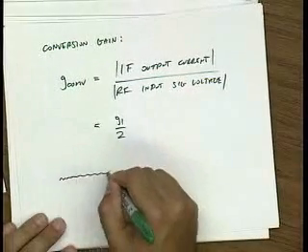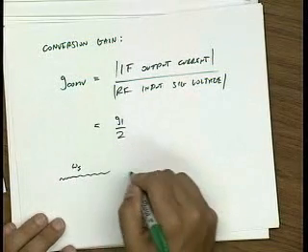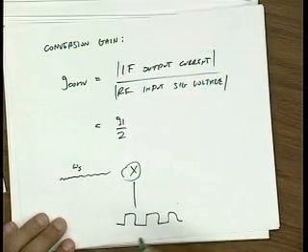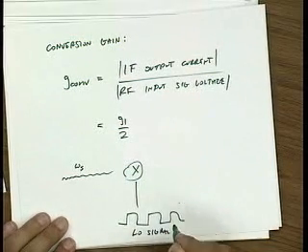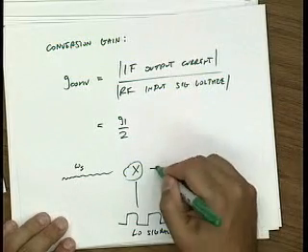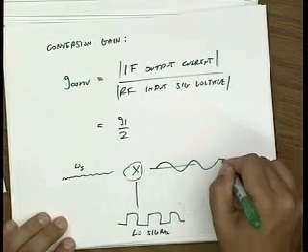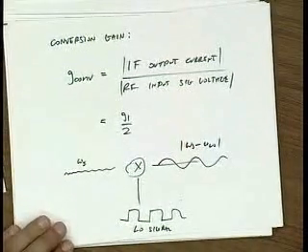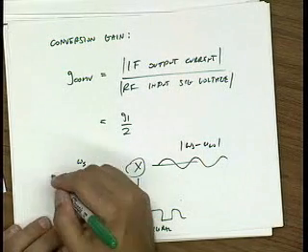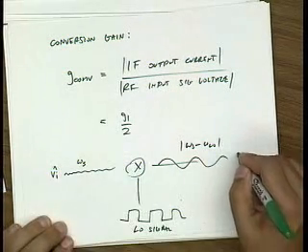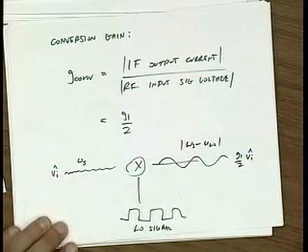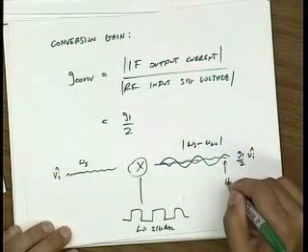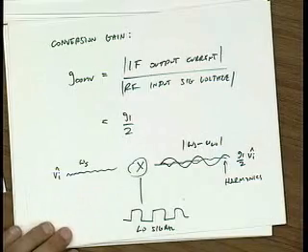So the input is small, at frequency omega s. It goes into the mixer. The mixer is getting pumped by this large LO signal. And the output, which could be larger since there could be gain, is at some IF frequency. Okay? And if this is magnitude V input, this current magnitude is G1 over 2 times V input. And there could be harmonics in here, but for now, let's say we filter out those harmonics.